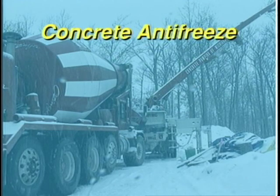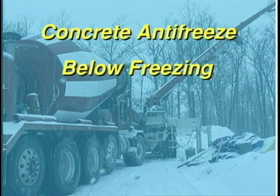Antifreeze must be added to the ready-mix concrete if the outside temperature on the day of the pour is below freezing.